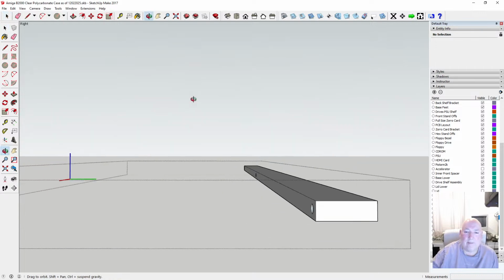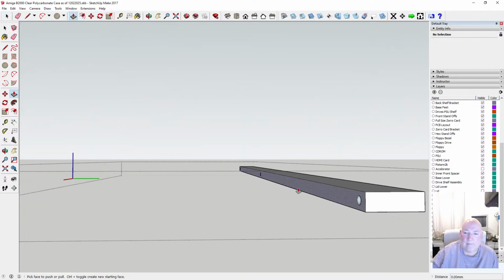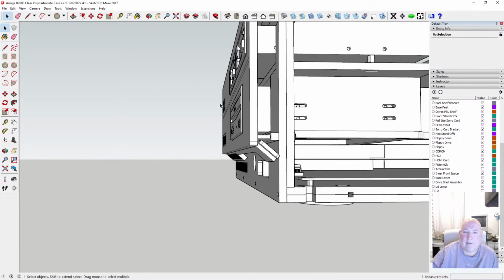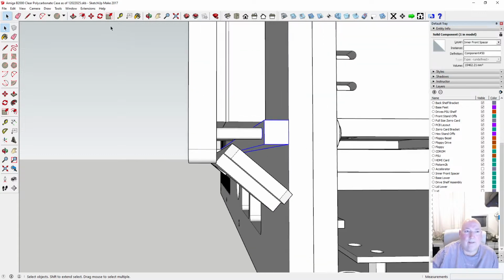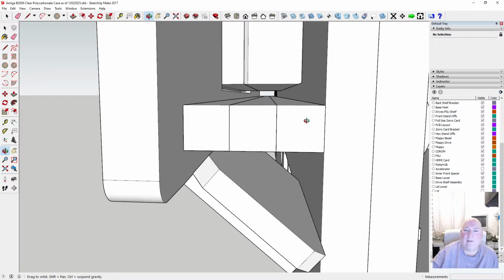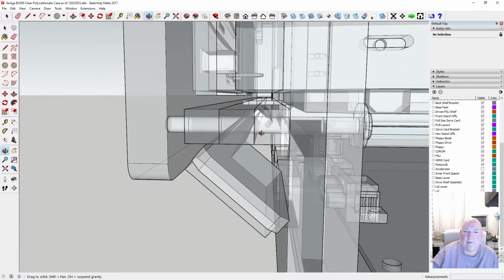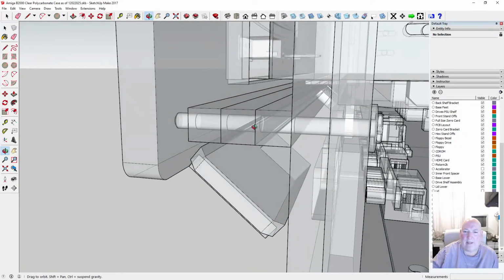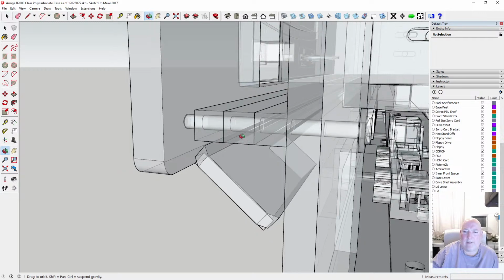Right, let's just do the same with this one. Back 12mm. Come out of it and copy it. 6mm forward and times 2. Okay, so that problem is gone. We don't have to try to drill a hole through a long piece and hold it stable. This can be laid flat now. I just drilled straight through.